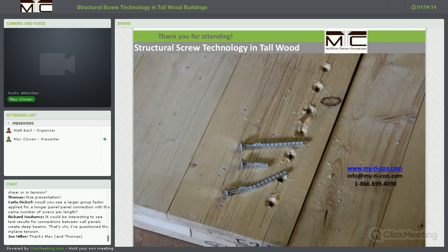I would say at one point there is a stop to the group effect because we have so many fasteners engaged in a load transfer that the specimen cannot shift anymore really. If we have many of these fasteners in there, it seems like the deformations in the connections get very small. We get a very high stiffness and a very high load resistance. And even if we were to have a group action factor of 0.8 or something like that in a connection, we have an overstrength factor of 3 or 3.5. So we would probably still be designing on the safe and conservative end for something like that.